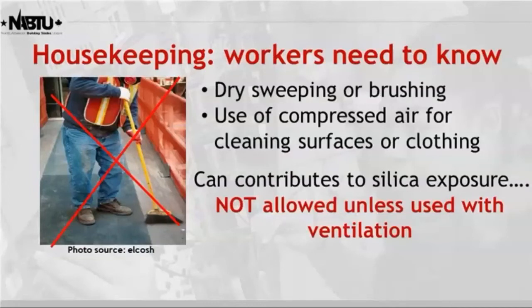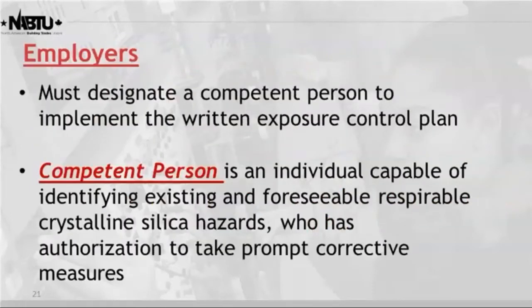Okay, and like I said, that small particle dust, the respirable dust, is what we're concerned with. So sweeping compound and/or vacuum systems or wet sweeping. In some cases you can use a different style broom and fog spray the dust as you sweep it up, or mist it. In addition, all employers must designate a competent person who will, once the control plan is written up, have as one of their duties to implement that exposure plan on the job site.